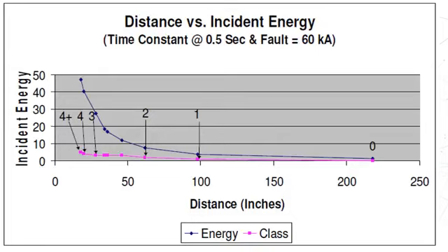So the hazard is increased. That means he now needs to be protected. The risk associated with that particular hazard is increased, so a new risk assessment needs to be performed. If the risk assessment already defined that you will perform thermography, visual inspection, or condition monitoring using any test instrument, and you identify any abnormality, you will rectify it.